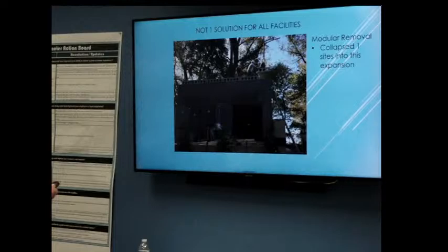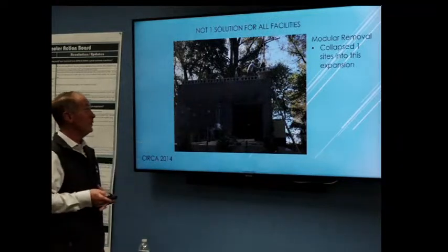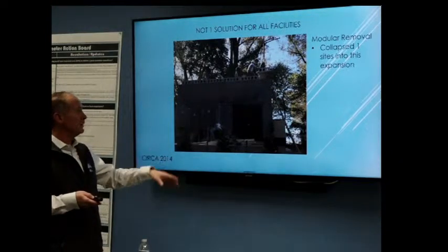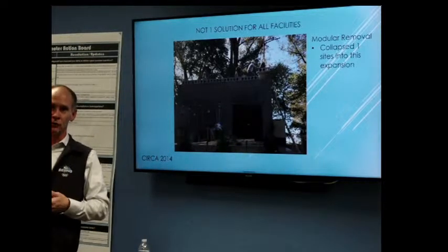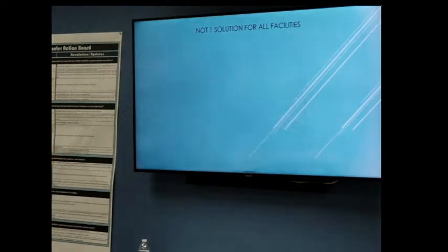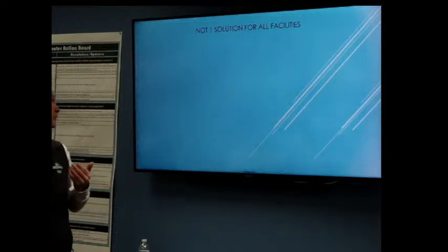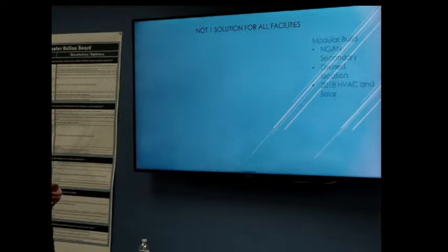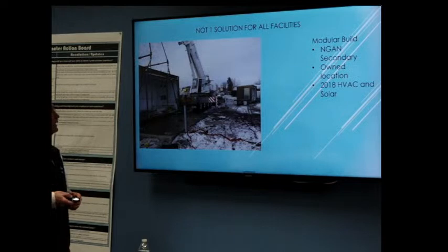And at the end of the day, you have what we would call a resilient hardened structure. You have a full CMU back building. You still have a new generator. The roof is watertight. It uses what's called pre-tensioned steel decking and planking. This actually creates a very good, robust roofing system. So that's just a second way that we deal with critical infrastructures and how we need to transition them during this broadband era. So we can look at another modular building technique.